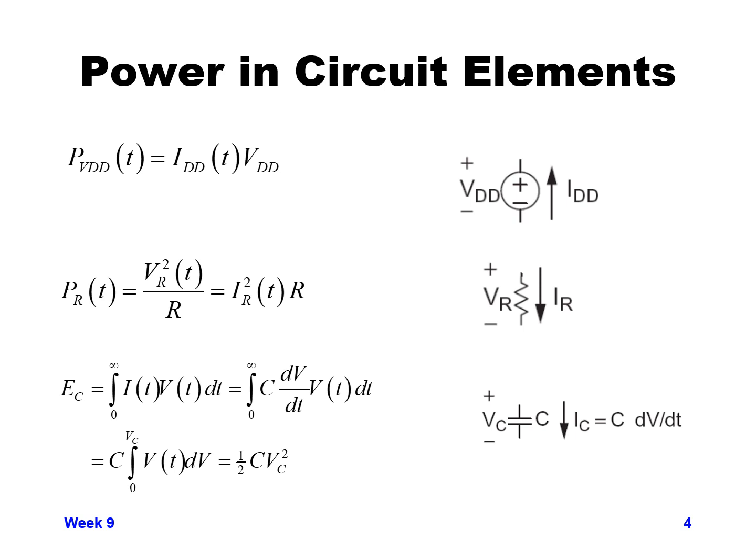The dt's cancel out, and we get energy is C times the integral of V dV. Integrating V with respect to V, you get 1/2 V squared. So your overall energy is 1/2 CV squared, whatever the voltage value is squared. So that gives us the energy stored in a capacitor.